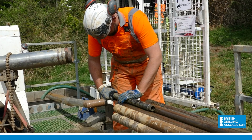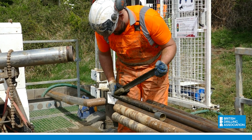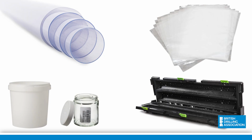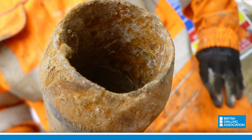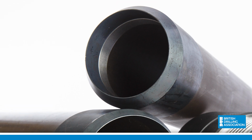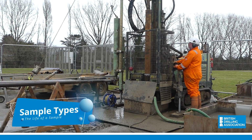Good preparation is the key to not only the efficiency, but also the quality of the sampling activity. This means the drill crew must have mobilised the correct samplers to the borehole location, and that there are suitable and sufficient tubs, bags, liners, boxes, jars, and labels available. It also means that samplers should not be damaged. All cutting shoes must have sharp cutting edges and have no nicks or dents that may compromise the ability to effectively sample the strata.